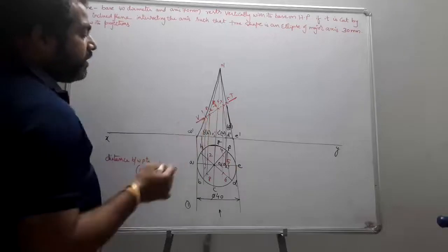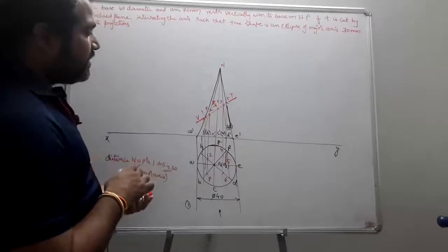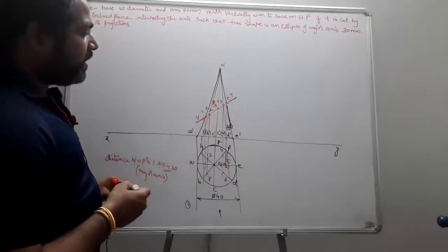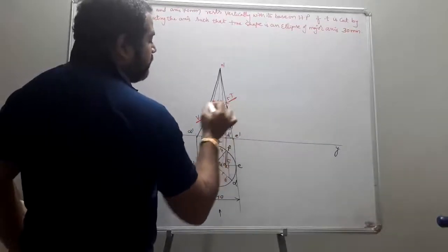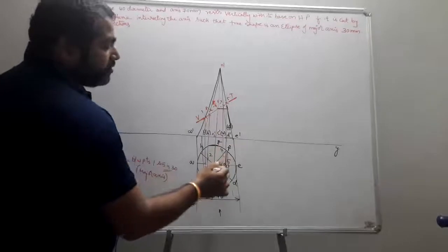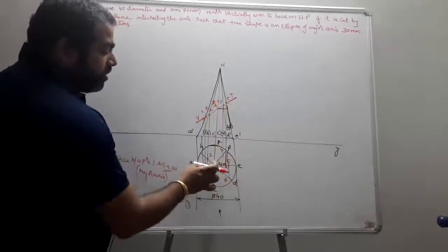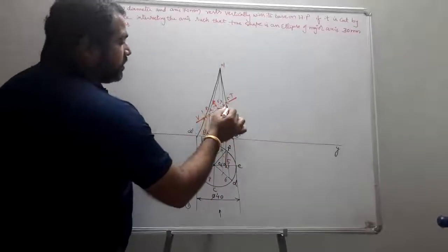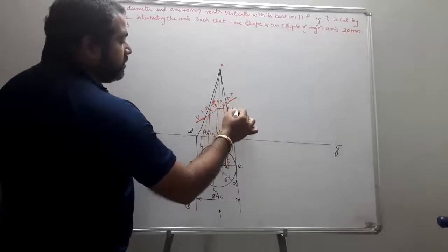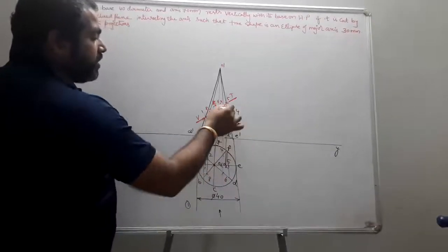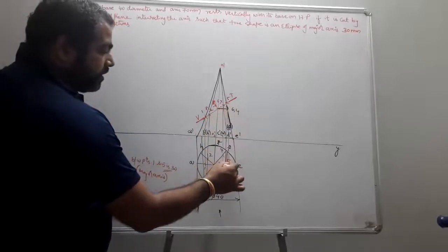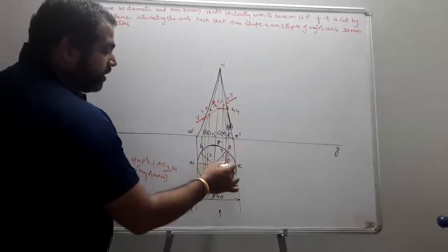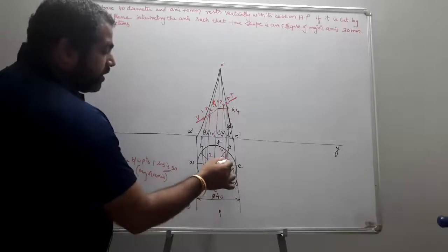Now let us see where points 6 and 4 are going to be obtained, which are not obtained here. So project the points 6 and 4 onto the true slant edge. What is the slant edge here? OE or OA. If you project those points onto OE, this becomes your point K. OK as radius, draw an arc.